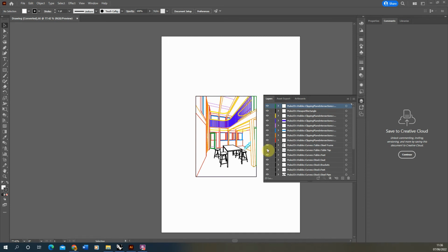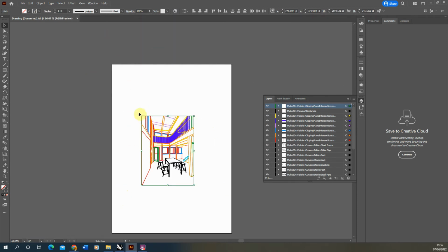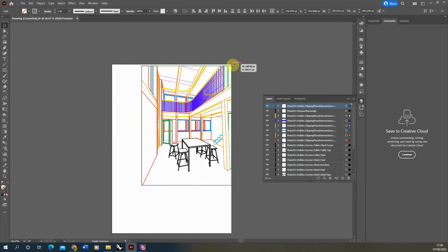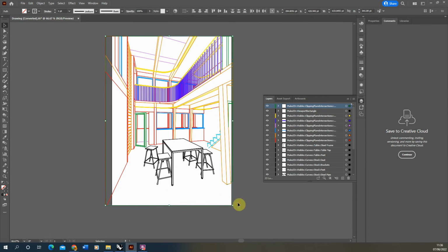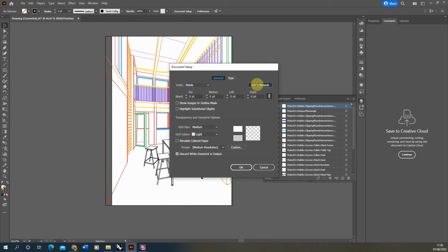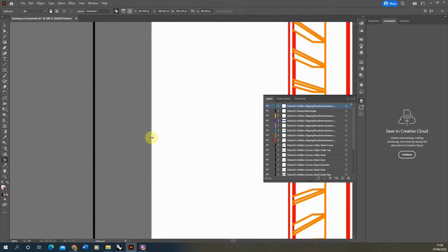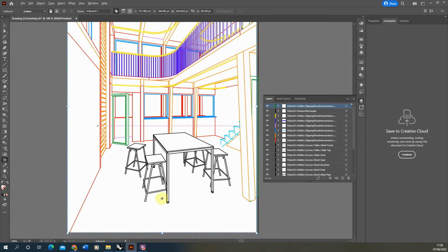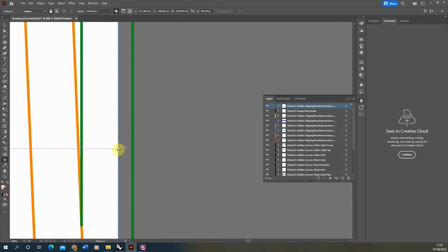Now we've opened up our drawing in Illustrator, we're going to begin by selecting the drawing that's coming in and resizing it to match our artboard. We can do this by holding the Shift key and selecting the top left or right anchors of this image and scaling it up to match the extent of the artboard. I'm not going to do this exactly for now because it will be a slightly different aspect ratio to what I have, so I'm just sizing it to roughly match, and then we're going to go to Document Setup, Edit Artboards, and then zoom in and line up that artboard to snap to the frame of the image, like so. We're just going to snap it to the center point of that line on each of these sides, checking that it's correctly lined up to that viewport.